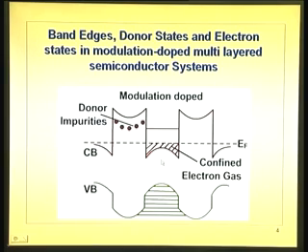First layer, you do not dope the gallium arsenide; dope this layer, do not dope it, dope it. It is very easy to do in MBE technology. As you finish the gallium arsenide layer, switch to aluminum gallium arsenide by letting in aluminum. If you are doing MOCVD, you just switch on trimethyl aluminum, you get aluminum gallium arsenide, and if you want to dope it, add sulfur-bearing compounds, sulfur monochloride or hydrogen sulfide. Then you get that layer doped.